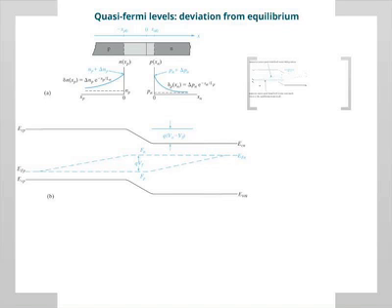But for electrons, because you have more electrons, the Fermi level gets closer to the conduction band. Remember, the concentration of electrons is determined by the difference in the Fermi level and the conduction band, right? Same definition for the quasi-Fermi levels as well. We will introduce this mathematically next Thursday, but I want you to understand this conceptually. So one would expect the Fermi level for electrons to go up.